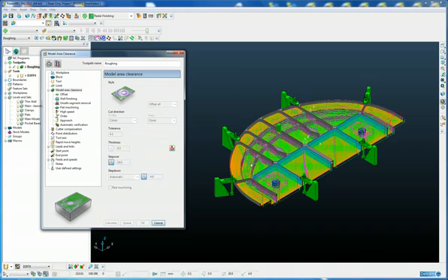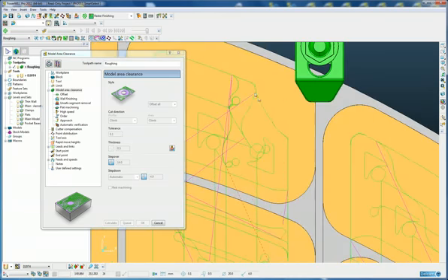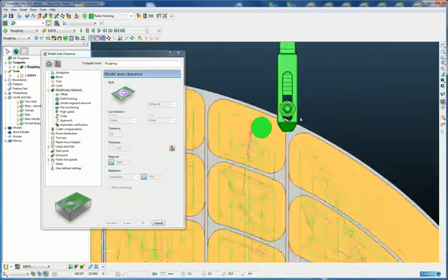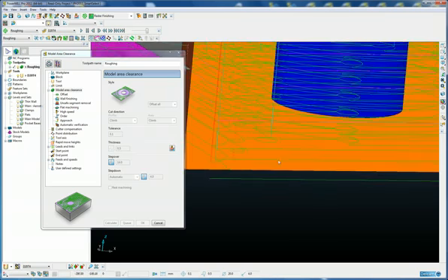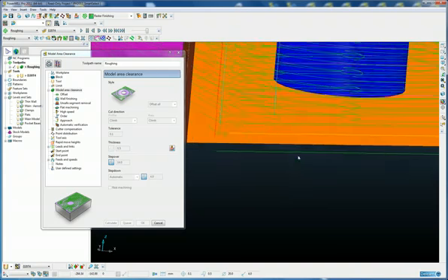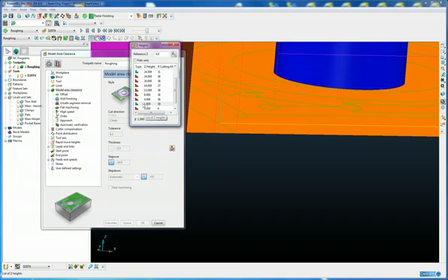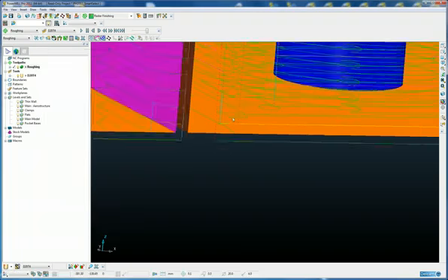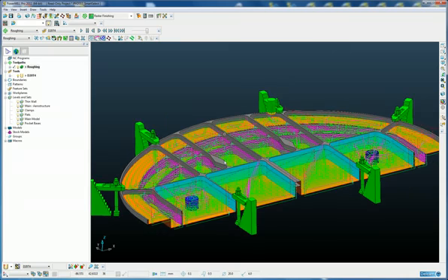So there's the toolpath calculated, and if we take a look from above and zoom in and I attach the tool somewhere here, we can see the 5 mm clearance we've put around the clamps. And if I zoom in here and select the bottom pass on the pocket and go to my view, pick Z heights, you can see that is at 1.5 mm. As mentioned previously, the big advantage of using Smart Selection is that the Smart Selection information is stored with the toolpath template.